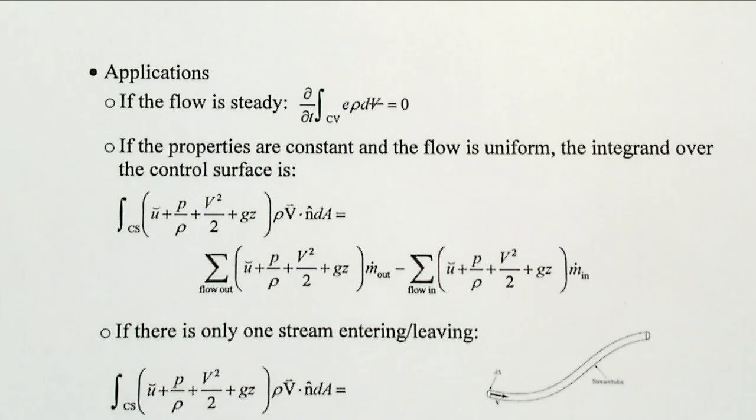You can say that, okay, V bar or average velocity is the same as the local velocity at each point, then I can say that rho A V is going to be m dot, right? But when the velocity has a profile that changes locally, you take the integral of that. You cannot say v bar equals v, because v is always changing, and you need to get the velocity average to find out how much m dot passes over the surface.